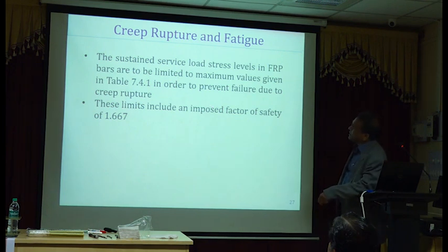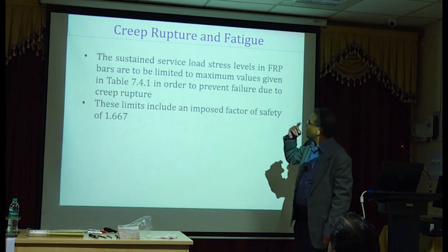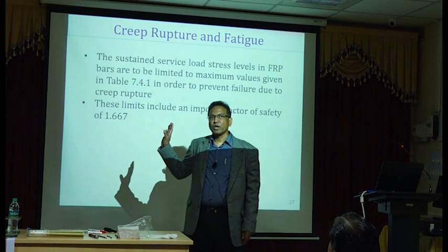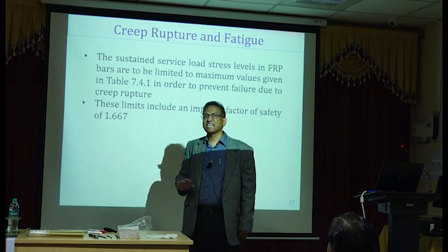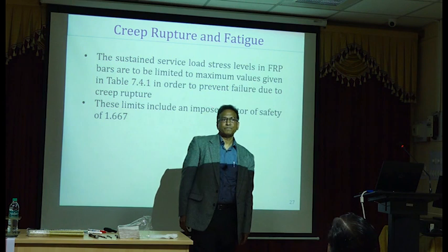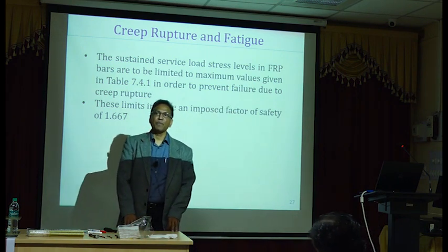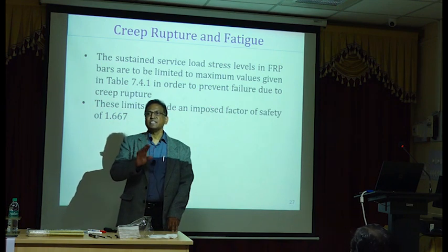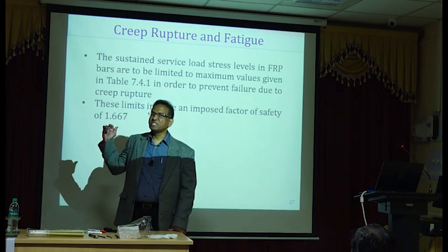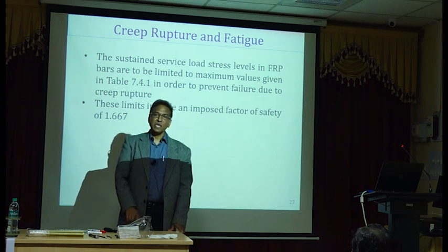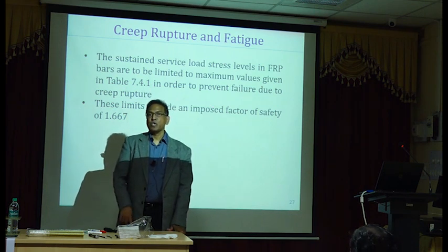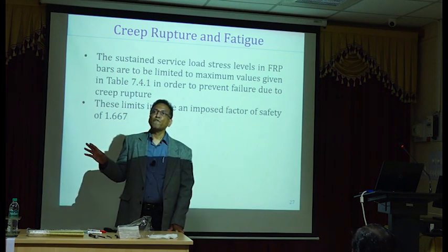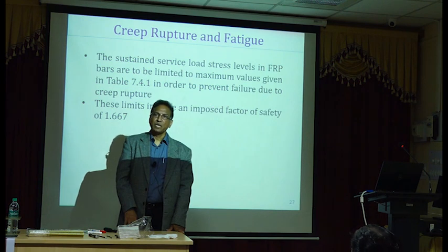That's the basis actually. Many times it's confusing to some people. ACI 440.1 classifies creep rupture as a service load condition. Very important to remember this, or make a note of that. ACI classifies the creep rupture limit state as a service load limit state. European standards consider creep rupture as a factored load effect.